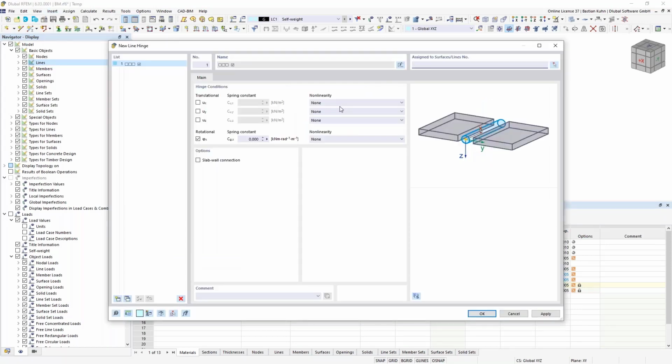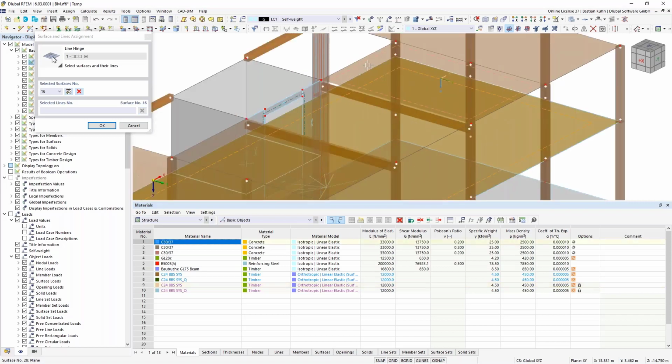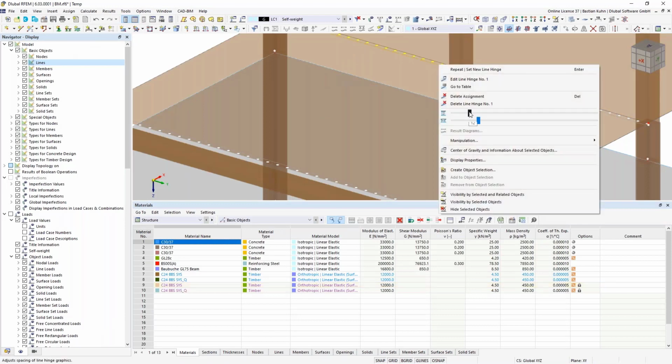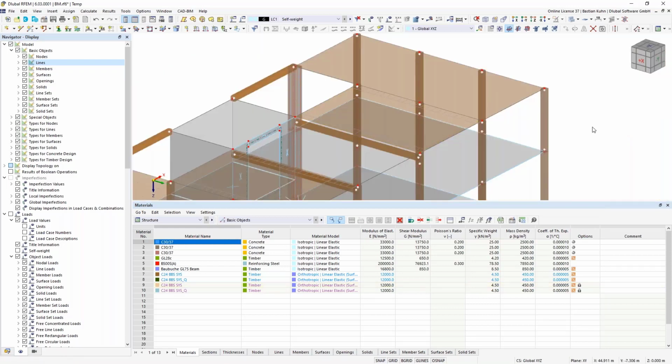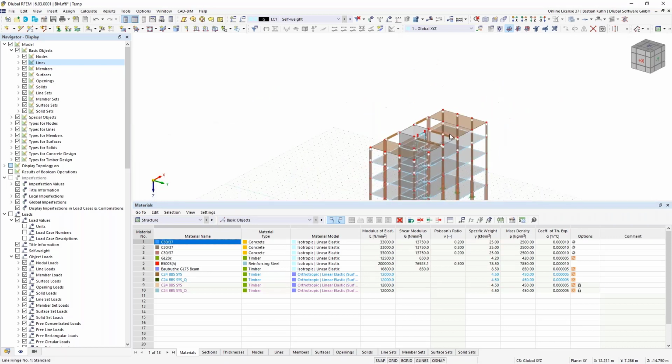I'm once again not explaining that in detail, but there should also be a slip in UX direction, but we will skip that and just use the moment-free rotation today on this surface. Okay, I hope I got them all. We can take a look. A little bit small in the displaying, but we can use the slide again to make that bigger. Looks good. So we have defined some degree of freedom in here.